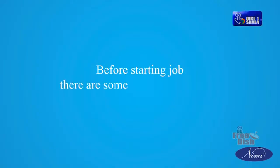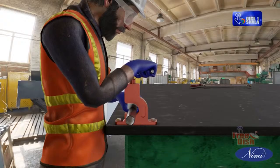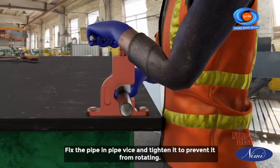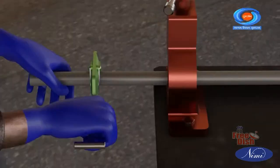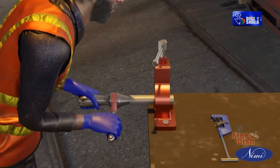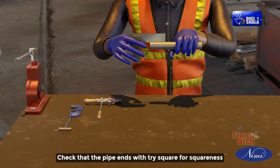Before starting the job, there are some preliminary checks to be made. Those are as follows. Hold the GI pipe in pipe vise tightly. Mark the required length as per drawing. Fix the pipe in pipe vise and tighten it to prevent it from rotating. Fix the pipe cutter on the GI pipe. Cut GI pipe for the required length using pipe cutter. Remove burrs using pipe reamer.